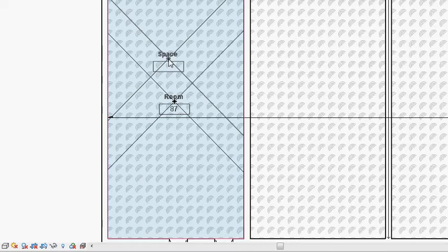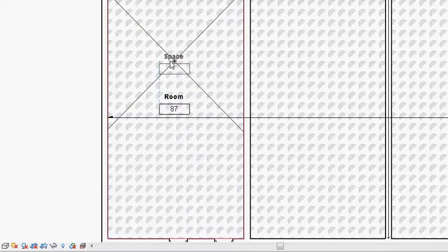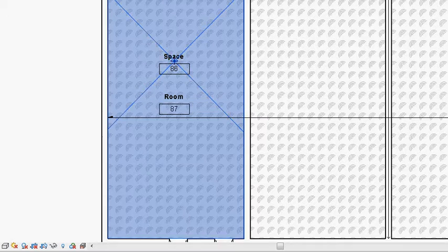So from my engineering side, I have to put the spaces in. For the architecture side, I place the rooms in, and then I necessarily have to place the actual space in the room correctly. Normally you have to tell it what the floor to floor heights are, and once you get to the floor to floor height, you have to go at least an additional 1/4 of an inch above it, just so that you cover your sliver space. That helps your calculations in Revit. So you have to make sure that stuff is correct.